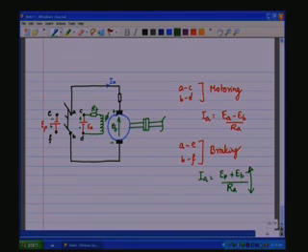It is like applying the armature voltage in reverse, which will try to make the motor rotate in reverse, which means it immediately has to come to a stop and then start rotating in reverse. So, when it comes to a stop, you just remove the double pole double throw switch such that IA becomes 0. Now, this can be pretty fast, and this is called plugging.